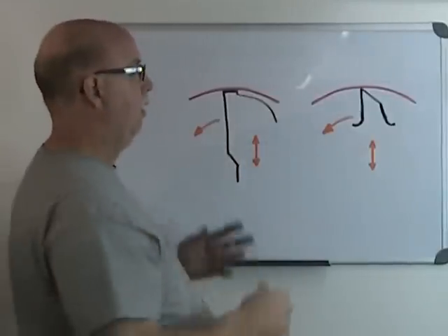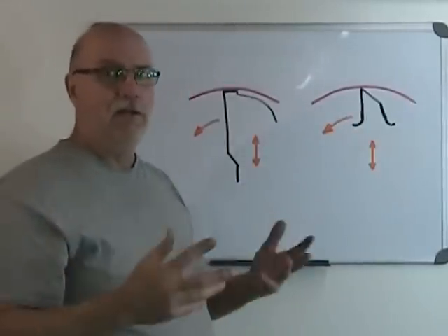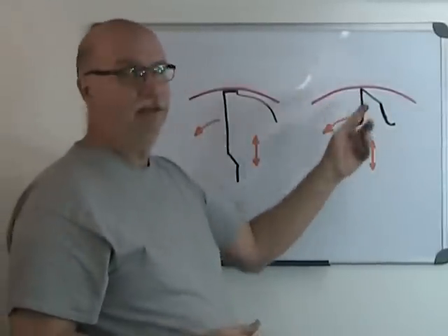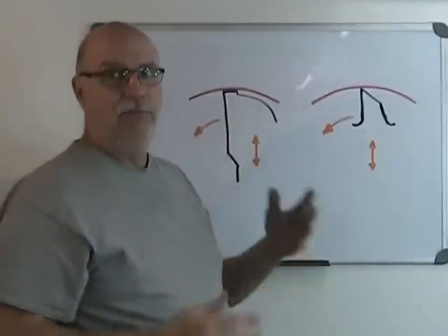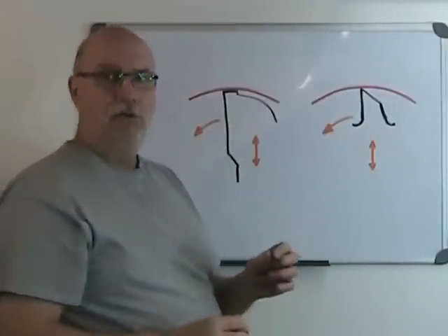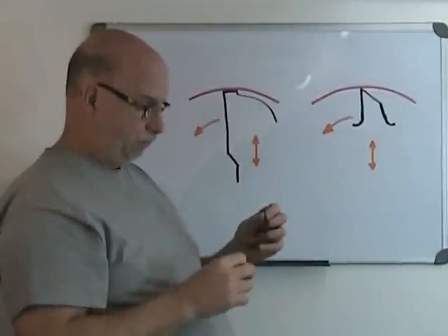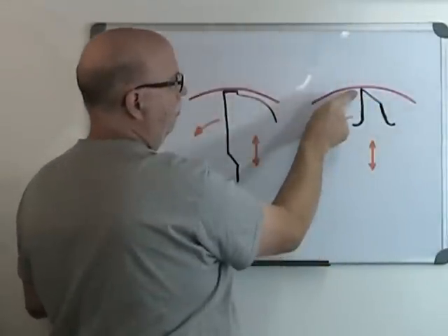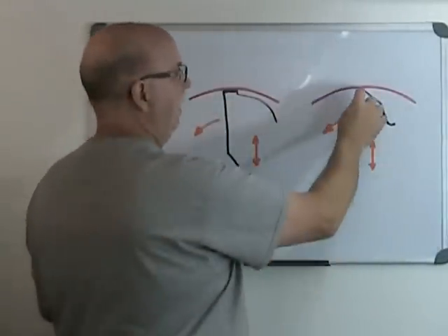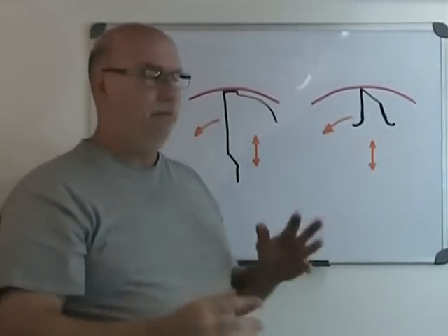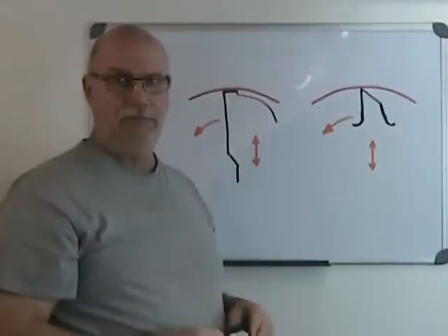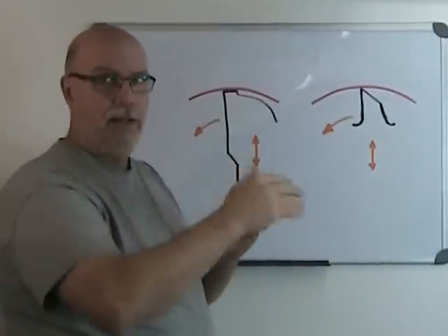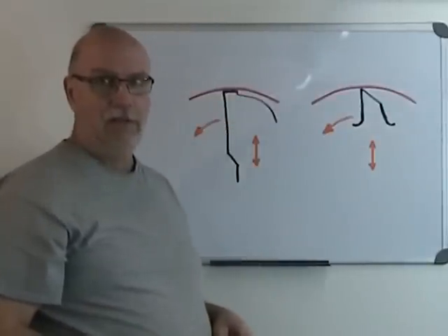It is round. Whereas with the reamer, we have a real cutting edge. And it's my fault if there's some confusion, because I have a tendency to call this a margin anyways, but it isn't. It's a cutting edge. So the tooth all along the flute of the reamer is a cutting edge. We have an edge, a point that comes right at the major diameter of the tool, and everything after that is in relief. So that means that this point can penetrate the surface, and that makes this a cutting edge, whereas this margin that is round and cannot penetrate the surface is not a cutting edge.